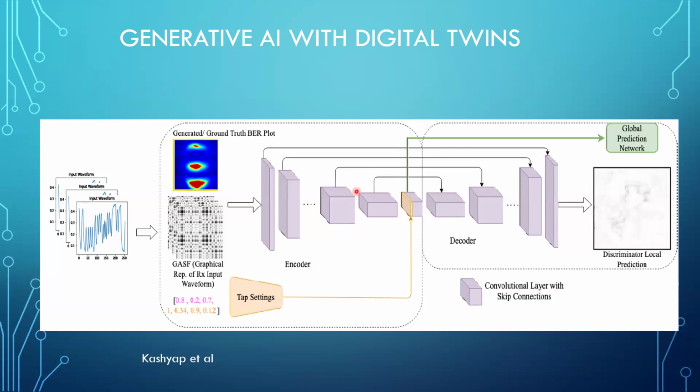So here the fake image is actually the output eye diagram of the high-speed PAM4 signal. What you try to do here is train the generator so well that the discriminator cannot tell whether it's a real channel simulation result or actually a fake image.